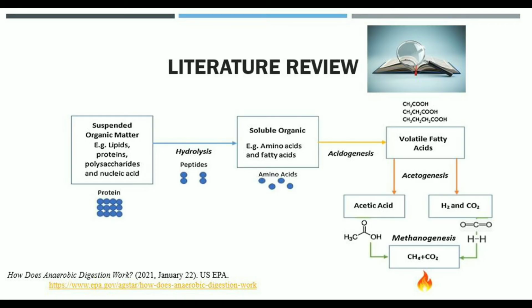Anaerobic digestion is a process through which bacteria break down organic matter such as animal manure, wastewater biosolids, and food waste in the absence of oxygen. There are 4 stages involved, which are hydrolysis, acidogenesis, acetogenesis, and methanogenesis, with the presence of their microorganisms for every stage. The organics that feed the anaerobic digestion process are composed of carbon, nitrogen, and oxygen. Microorganisms use those organics as a substrate for growth and combine them with water to form biogas. Anaerobic digestion reduces the volume of the waste, produces biogas for energy, and provides a byproduct that can be used as fertilizer.